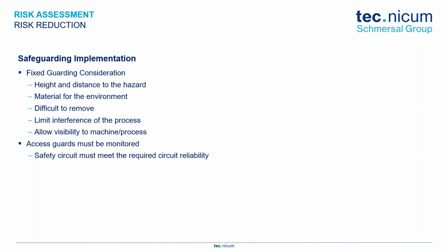And if you identify a hazard that can have a risk of a fatality, and we say, okay, you know what, we're gonna add some safety devices on here, and you order a light curtain that is not the proper level of safety. So those of you who understand types of light curtain, you order a type 2 light curtain instead of a type 4, or you only wire up one output to a non-safety monitoring device.